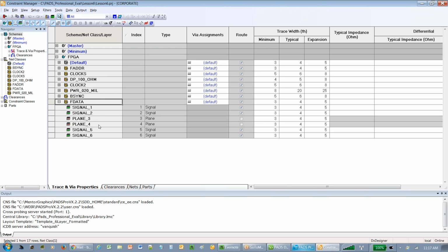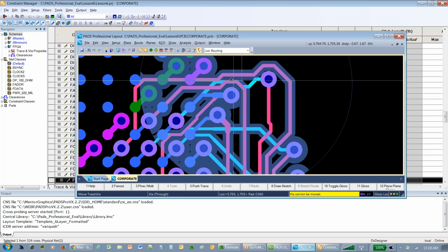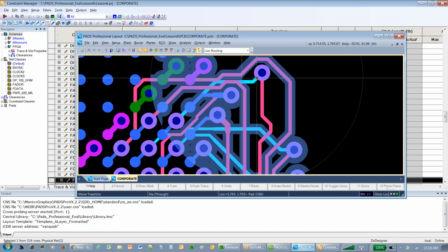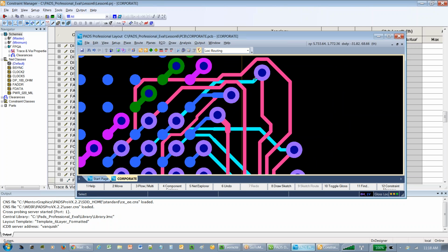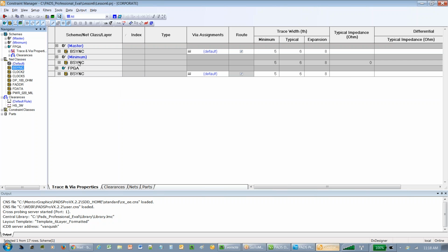So for particular nets that are coming out of there, I can specify rules by layer just under that part. That's what rule schemes are: you're defining those rule areas on the PCB to make your life easier. As I pull an item around, it's going to automatically change as I cross that boundary for that particular area.